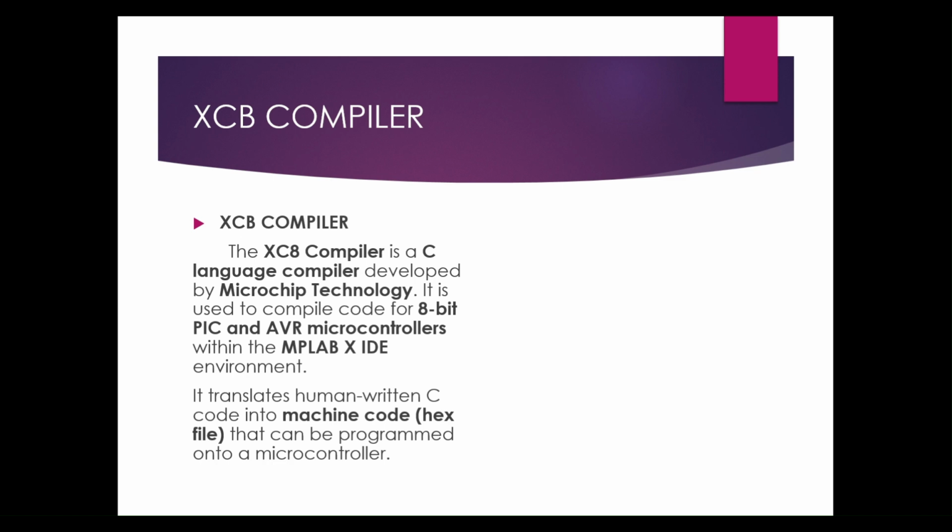XC8 compiler: the XC8 compiler is a C language compiler developed by Microchip Technology. It is used to compile code for 8-bit PIC and AVR microcontrollers within the MPLAB X IDE environment. It translates human-written C code into machine code, for example a hex file, that can be programmed onto a microcontroller.